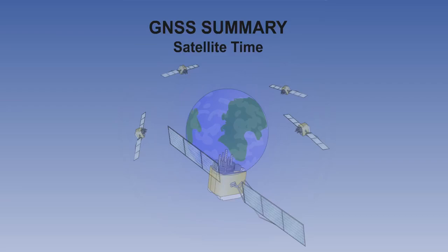There are 3 standards of time used in GPS. The satellites all have highly accurate atomic clocks, internally correct to within plus or minus 1 nanosecond. They are kept within 1 millisecond of GPS time. GPS time does not coincide with UTC. The difference is contained in the navigation message. Finally, there is UTC, which is the time actually displayed to the user.